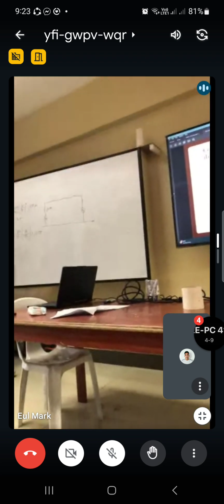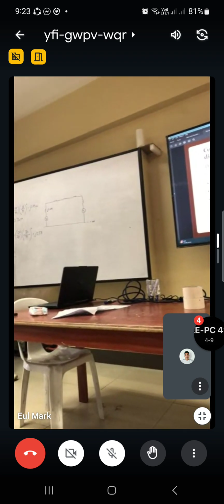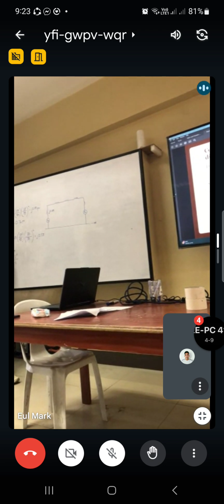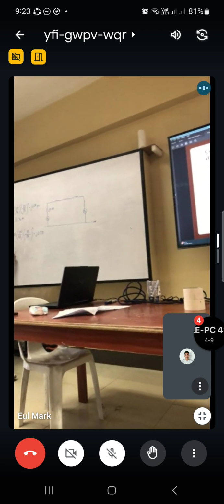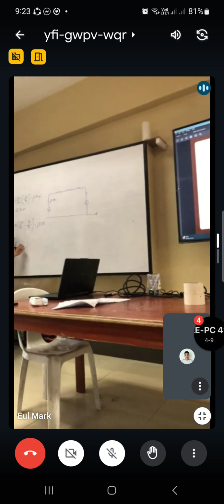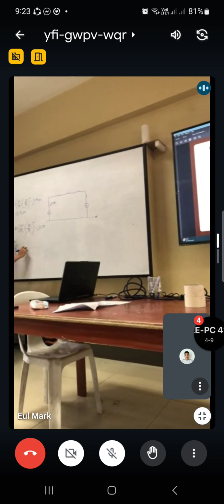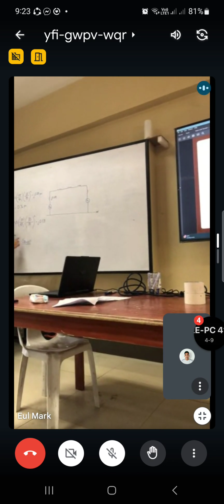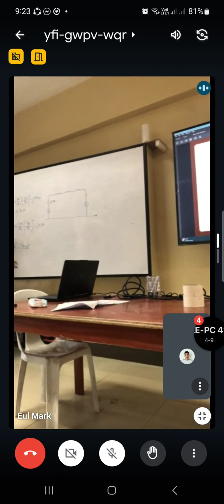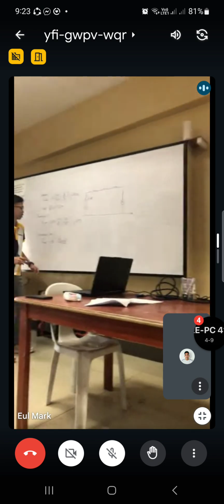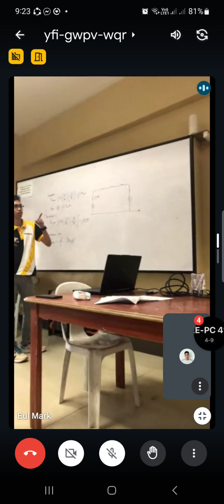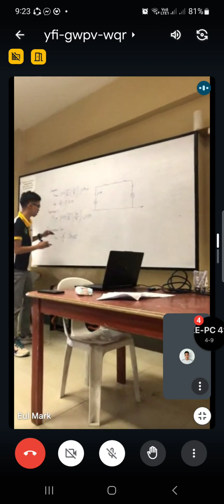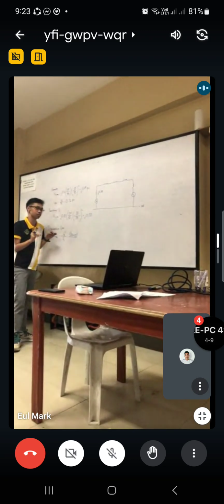For the base here, it's zone 2. So this is equal to 20 squared. Actually you can use 20 squared, but let's make it proper, because sometimes others make mistakes. The S base is 100 kVA, so 20 squared over 100.